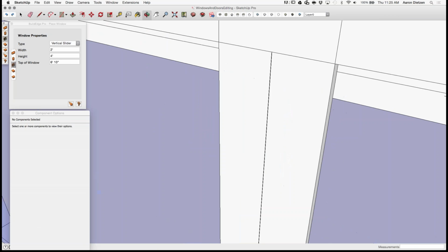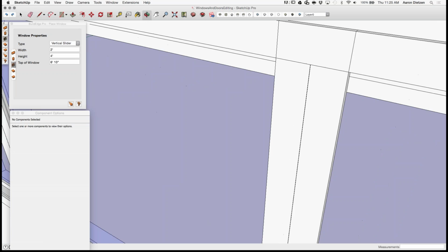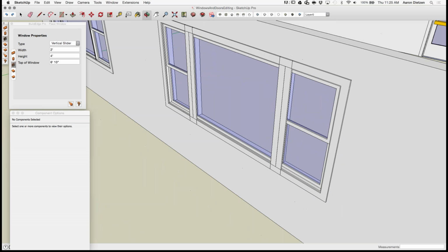If I zoom in super tight, I can actually see that 0.01 inches. So this is the one window, this is the other window. They don't quite overlap. There is logic in there that says I can't punch 2 holes in the walls that lap over each other. I do have a request into our development group to address that, to allow me to butt the 2 up against each other so I have a single line between, and it seems like that should be possible, but it doesn't have that right now. So right now I do have this little teeny tiny gap. Fortunately, by the time I come out to any reasonable distance, it disappears.